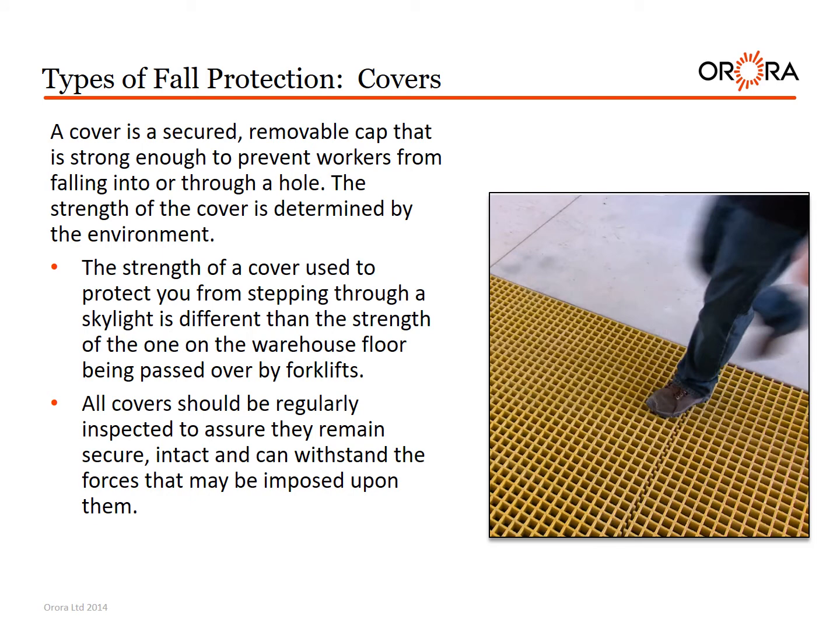Types of fall protection. Covers. A cover is a secured, removable cap that is strong enough to prevent workers from falling into or through a hole. The strength of a cover is determined by the environment.